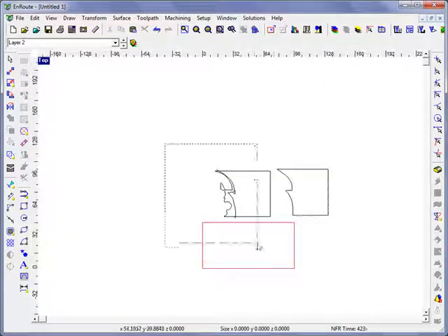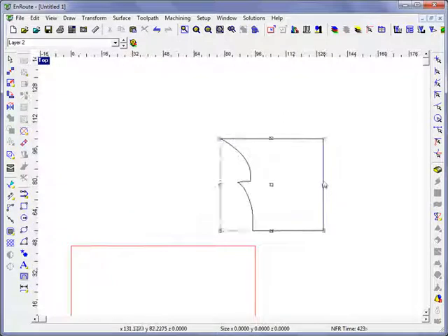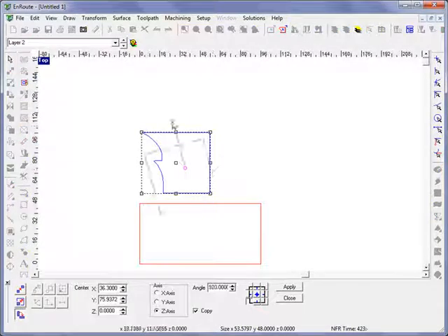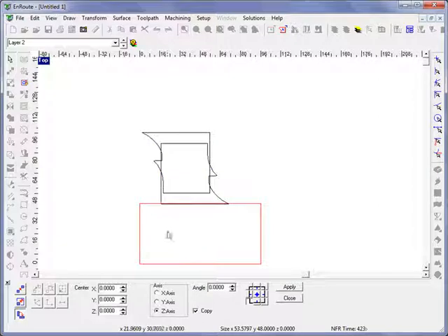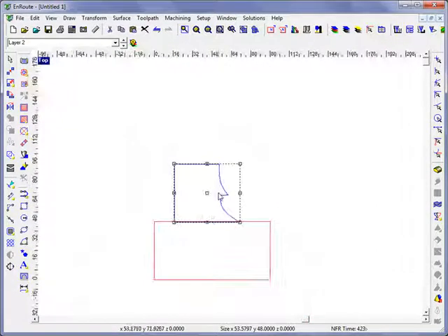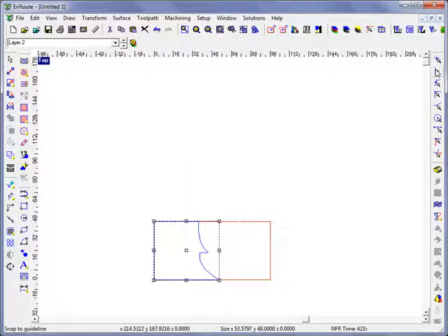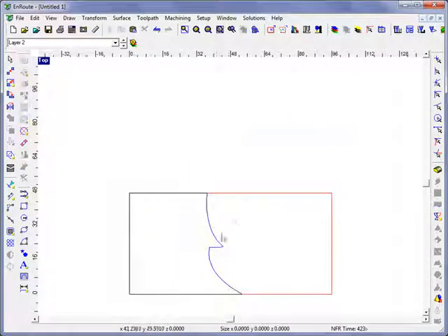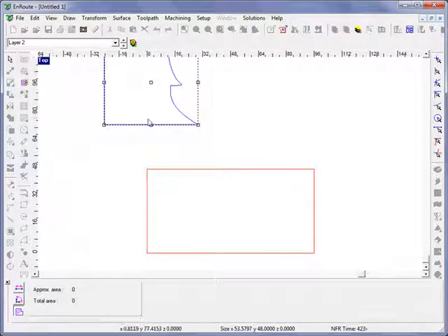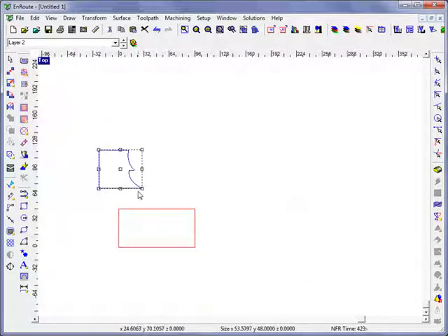Once you have this particular geometry, which would be considered a remnant, I might even want to first of all rotate this, and make it easy to set a home position. I made a copy here. I'll hit Control 1 to move it to the lower left-hand corner of the plate, and I can store it with a little bit of information, such as the overall area of this part, and store it along with other geometries that I could easily recall and turn into a plate.